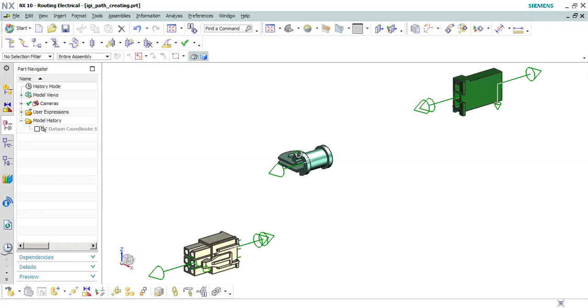Spacing clips or clamps too far apart can cause a rattle condition. Gravity also plays a part in securing the harness. Safety is the most important requirement. You can start to see why you need to gather all the information of the configuration before starting your design of the wire harness. Okay.